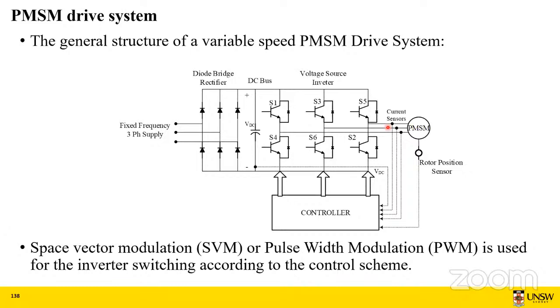How does the speed increase? By increasing the frequency of your rotating magnetic field. That's the main task of the inverter in a variable speed drive. You get variable voltage and frequency at the output, so that the synchronous motor can start without any trouble.